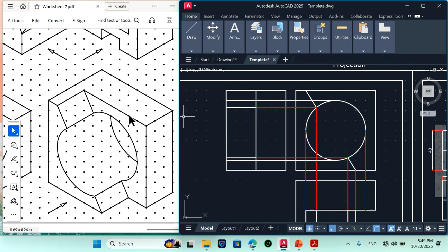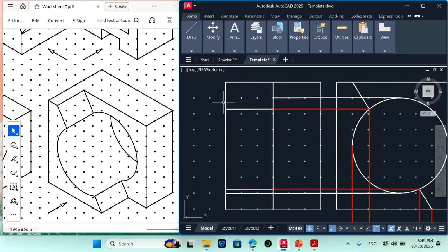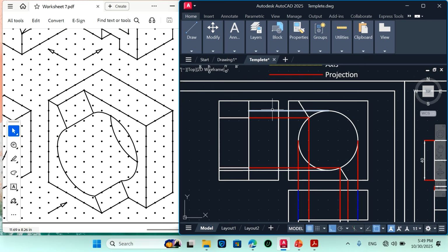Now if you see the side view, this curved surface, this inclined surface I already drew, but there is no other material to hide this surface, curved surface, till here. But here, this surface is hiding till here. That means till here this surface is hiding the curved surface. So till here hidden line will be there, but here there is no material to hide the surface. So I will be trimming this till here. Okay, so this is only hidden line from here to here.